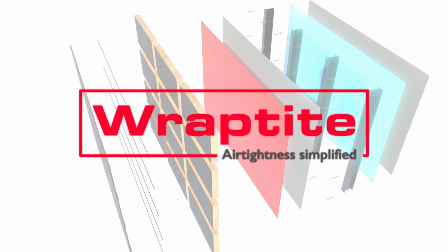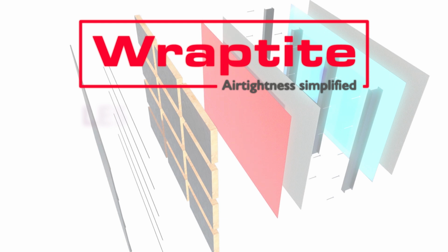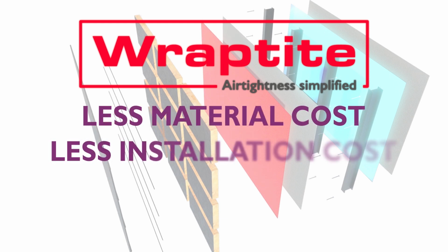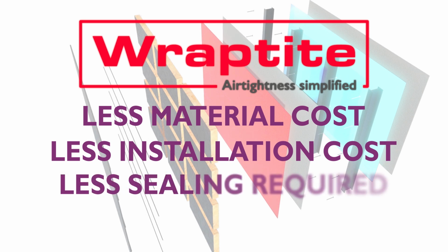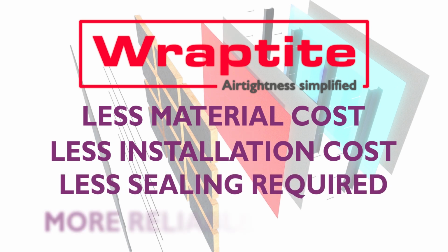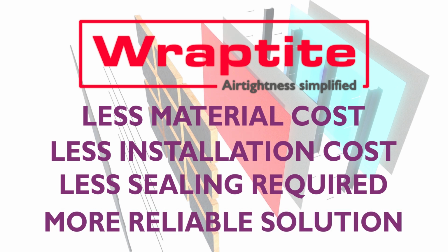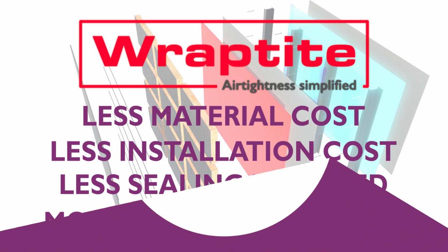By removing the vapour control in favour of an external air leakage solution, we achieve a few things. Firstly, we remove the associated material and installation costs, but more importantly, we remove the need to seal all the surface penetrations, meaning we have a more reliable air barrier and can reduce the air leakage rates used at the design stage.